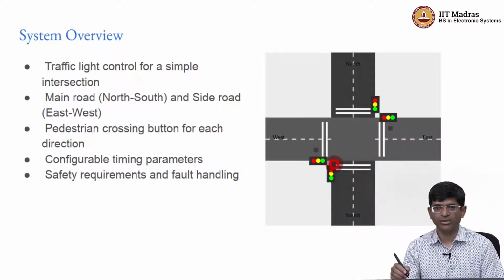I need to give everybody time to stop and then activate. So, what will happen is I initially have a north-south green, I then go to a north-south yellow and then red. At that point I have red on north-south and red on east-west, so no traffic is supposed to go in any direction, but once that is done I can then turn on the east-west green light and proceed.